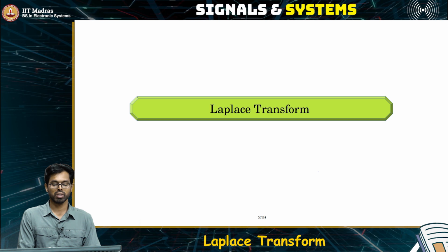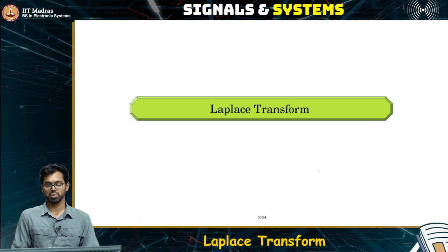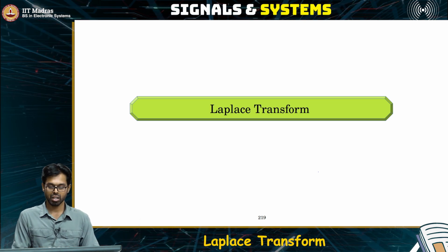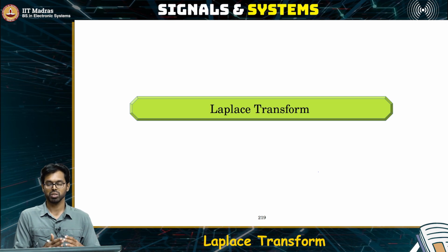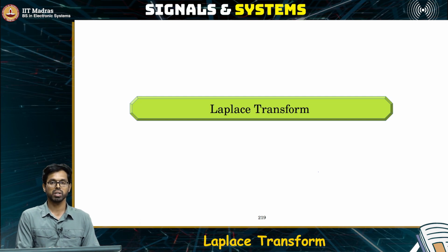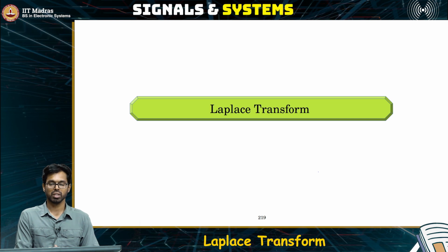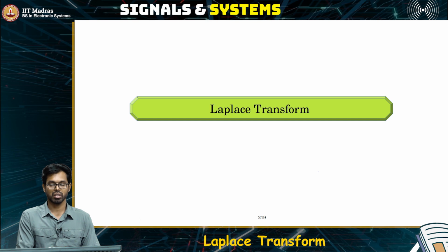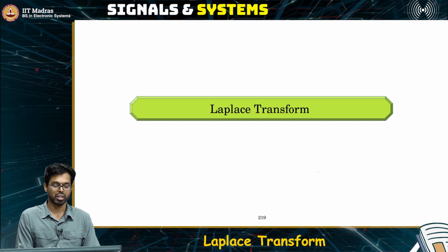So finally what we did was we just applied this Fourier transform to RLC circuits which are in the form of impedances, and we had a rational expression as the frequency response. So if we wanted the frequency response, we can just stop there, or we use partial fractions and then find out the impulse response. Once the impulse response is known, then we can compute the output of the circuit for any possible input just by convolving with that. So this is the main usage of Fourier transform for us in electronic circuits.